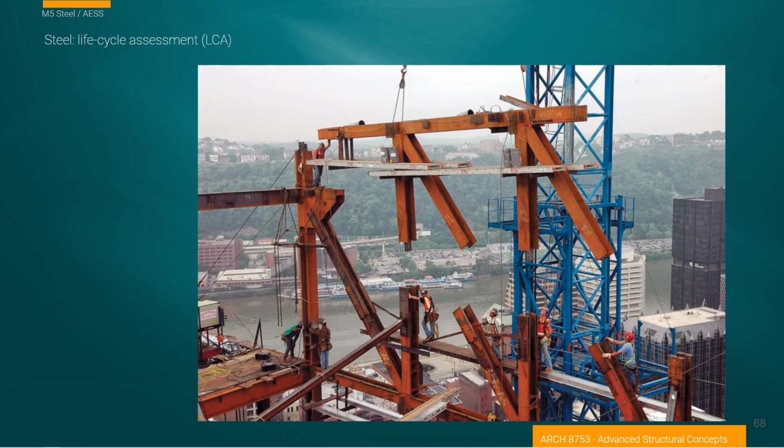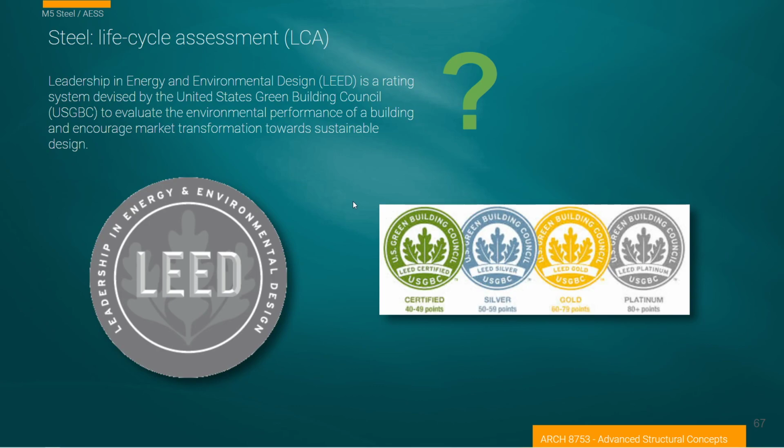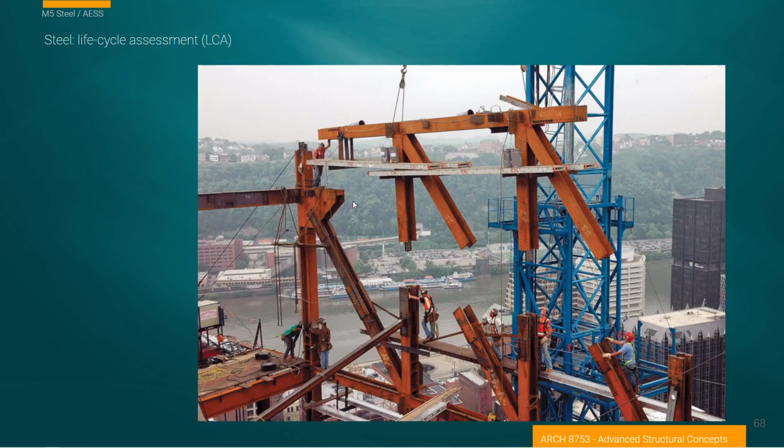But there are things to consider about the value of steel, and I'm only kind of introducing this. Steel lasts a long time. It's very recyclable. It has high performance characteristics. A lot can be done with it in the field, and even in many ways more than can be done with timber as far as misalignment and corrections of field problems, because we can weld steel together and then transfer loads very effectively. If we have a piece of timber that's too short, we can't weld extra wood onto it.